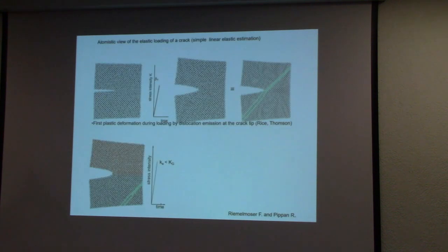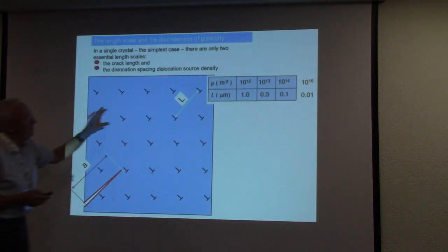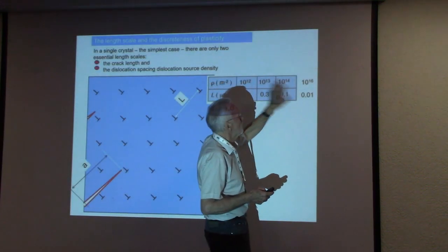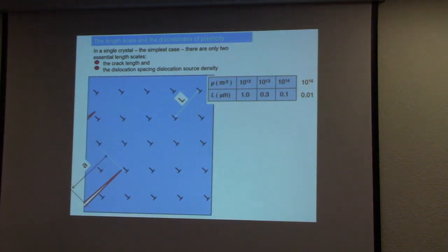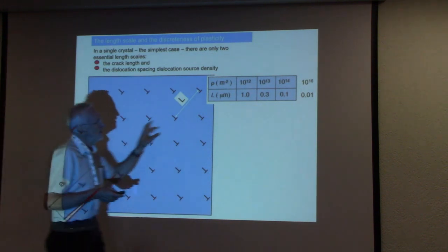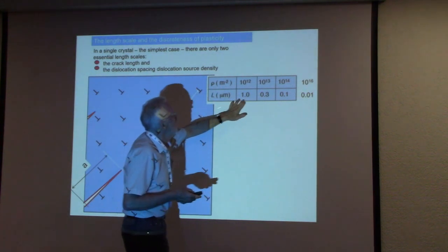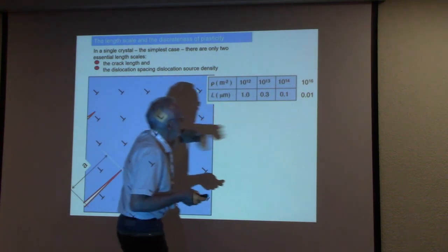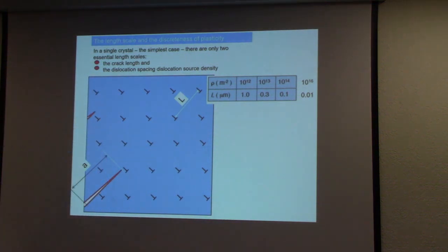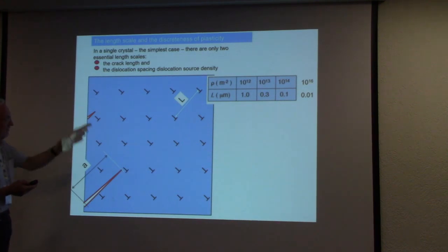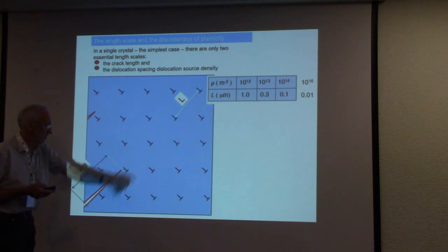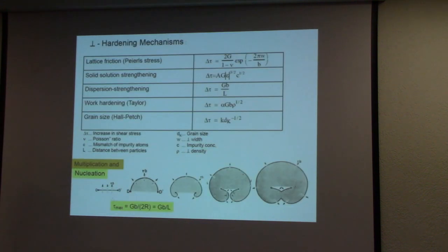If you have heavy plastic deformation, then your spacing is quite small, so you can use the standard elasto-plastic concept with Mises plasticity, even at significantly smaller scales. But when you have only a very small dislocation density and very small loads, it is most probable that you will not find dislocations in front of the crack.